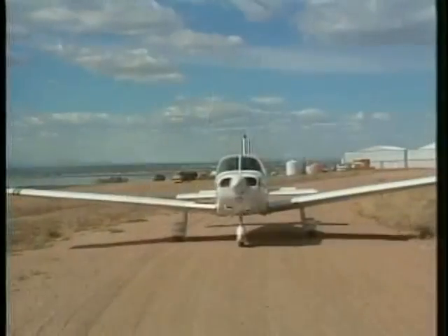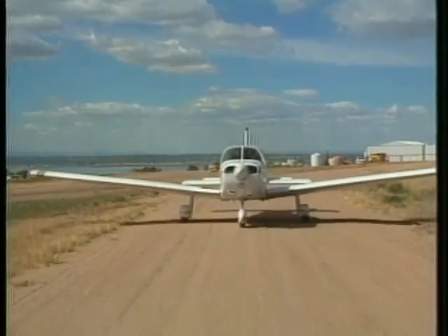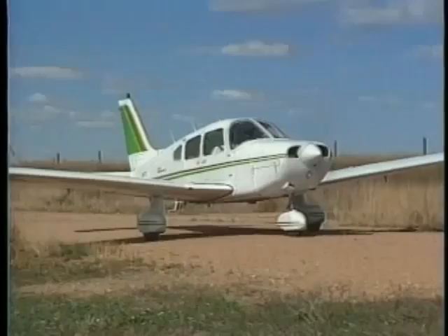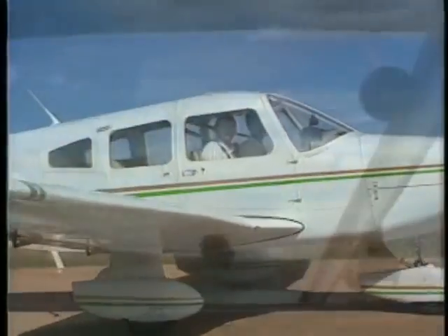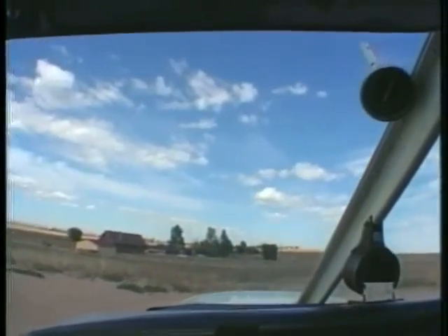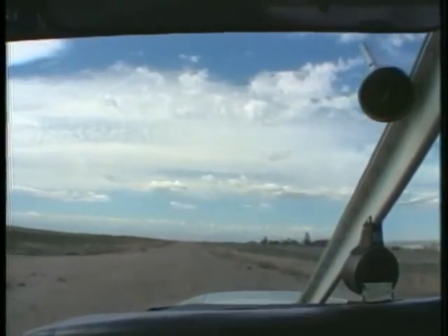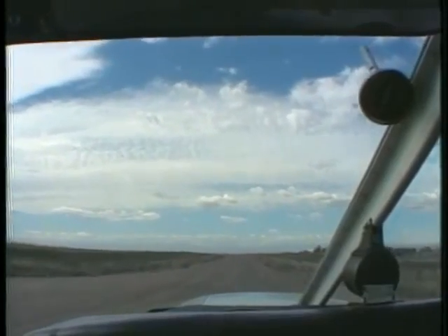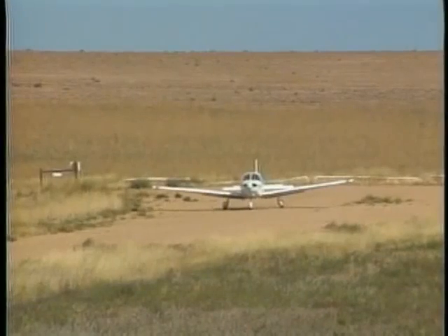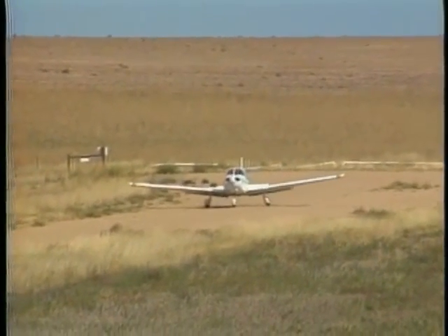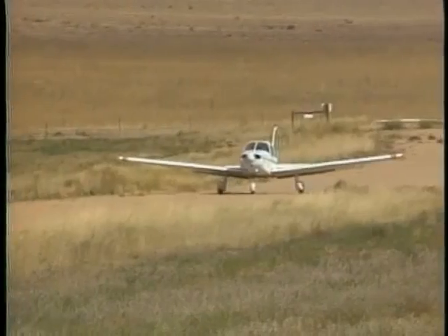You can relieve some of the weight on the nose gear by holding the control wheel in the full aft position. Before you taxi onto the runway, however, make sure the traffic pattern is clear and that all pre-takeoff checks are complete. If the approach and departure paths are clear, taxi onto the runway. When you're aligned with the middle of the runway, smoothly apply full throttle. As the engine reaches full power, check your engine instruments to verify proper operation. Continue to hold back pressure on the control wheel and maintain positive directional control. The rudder will become more effective as your speed increases.